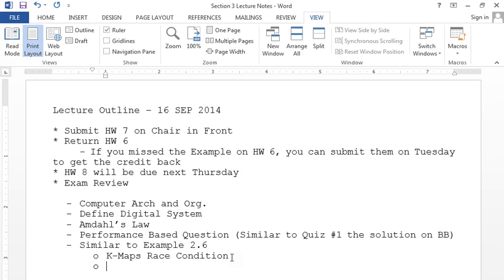4, exactly right. And so if it's A and B, what's my literal cost? What's my gate cost? 1. Because they're together, it's one gate. They're smushed together, separated by an OR. That means OR is further cost on input. So we have 2, 1, and what's my inverter cost? 0. So if I have 4 and 3, what's my total cost? 7. 4 plus 1 is 2 plus 1 is 3. Yeah. So it's going to be 7. So why am I not counting the B map and gate?